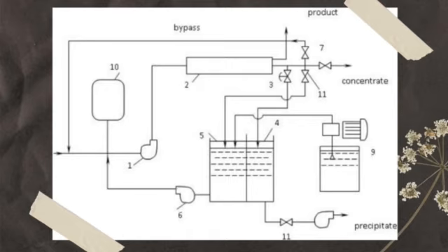The RO concentrate was continually flowing through the precipitation reactor, which contained seed crystals. By infusing caustic solution into the RO concentrate, seed crystal formation was started.